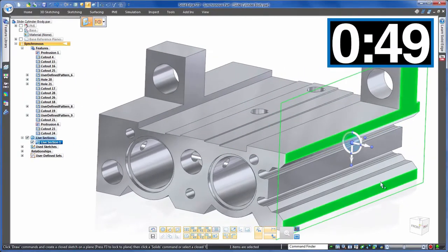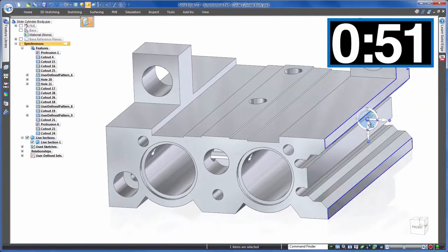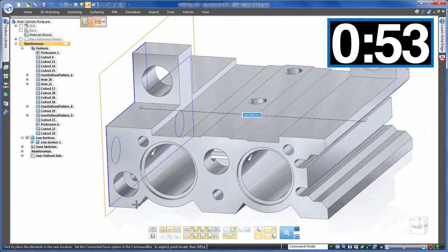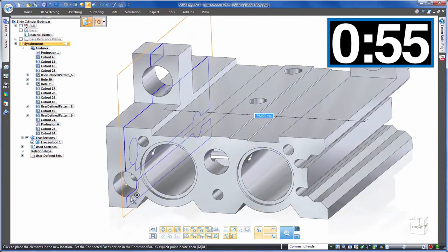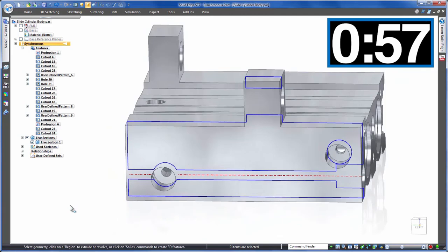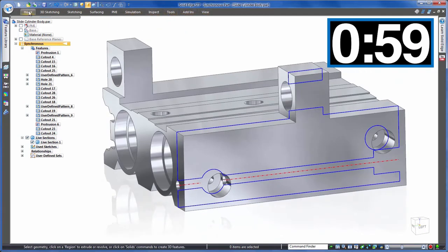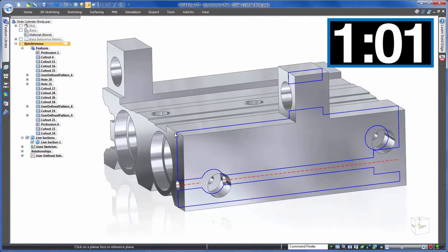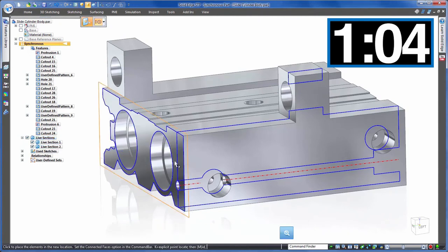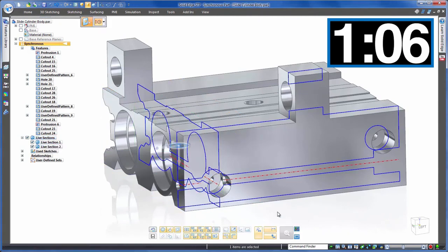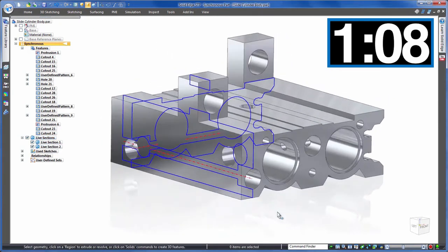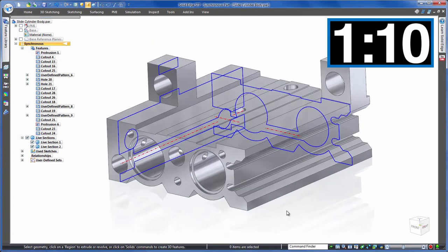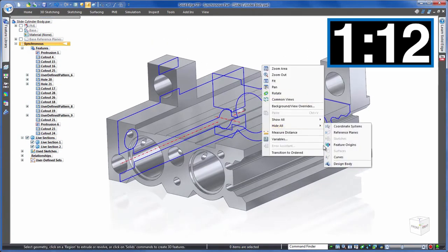And this same final edit using synchronous technology, we'll remember the section view that we used in our history-based approach. Well, check this out. Synchronous technology automatically creates sketches at that particular section, allowing us to use those to drive the model. And as it's that easy, well, let's add 2 sections. We can even hide our part so that we're left with an unobscured view for our required edits.